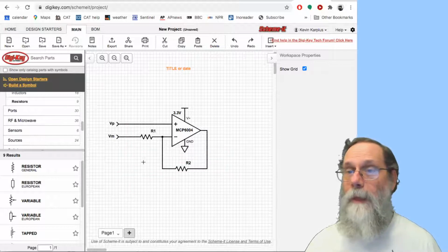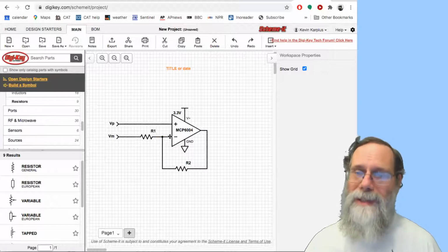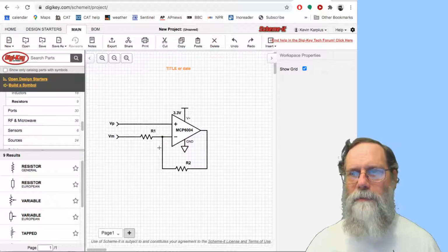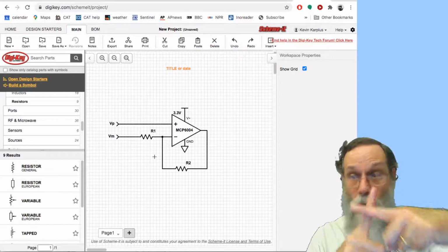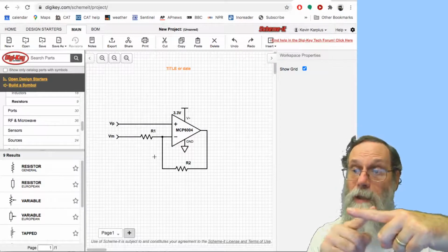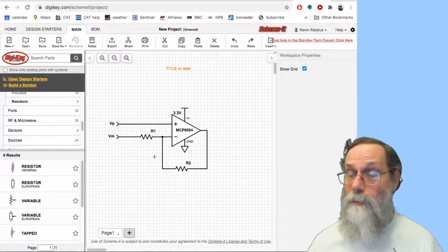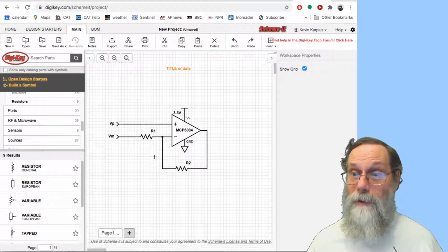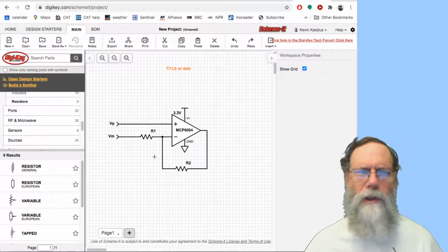Just get rid of all that. But if you want things to be connected, there must be a connection dot. Missing that connection dot would indicate, well, since it's a T connection, it's not a serious problem for the connection dot to be missing. But if it was a crossing line, 2 wires crossing each other just like that are crossing, they're not touching. You want them to connect, you have to put that circular dot there. Very important when you're doing it by hand too, because it's very easy to have things that are close but aren't supposed to be connected, close but they're actually supposed to be touching and connected. Put the connection dot in if you really need a connection.